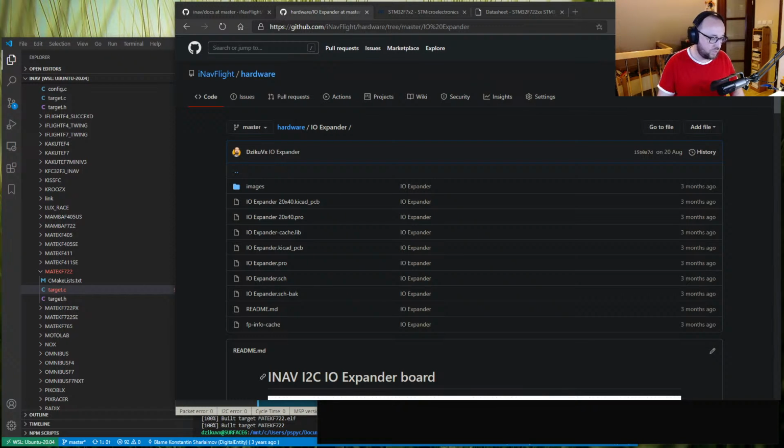Cursed FPV has a question about the Matek H743 and M9N and how screwed he is. In case of the H743, yeah, you are kind of screwed because probably INAV 2.6 will be released without H743. However, the driver for the M9N was already merged, and INAV 2.6 will be released with this driver. And even my Pirk 7 already has the Matek M9N GPS over here.